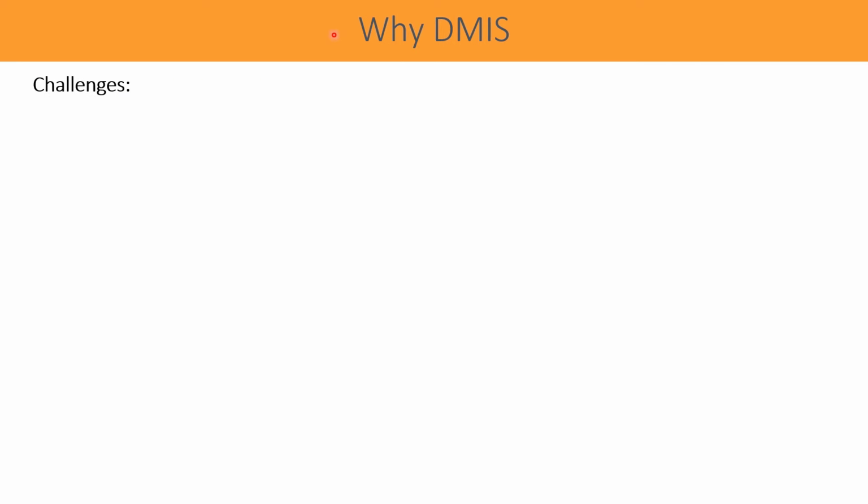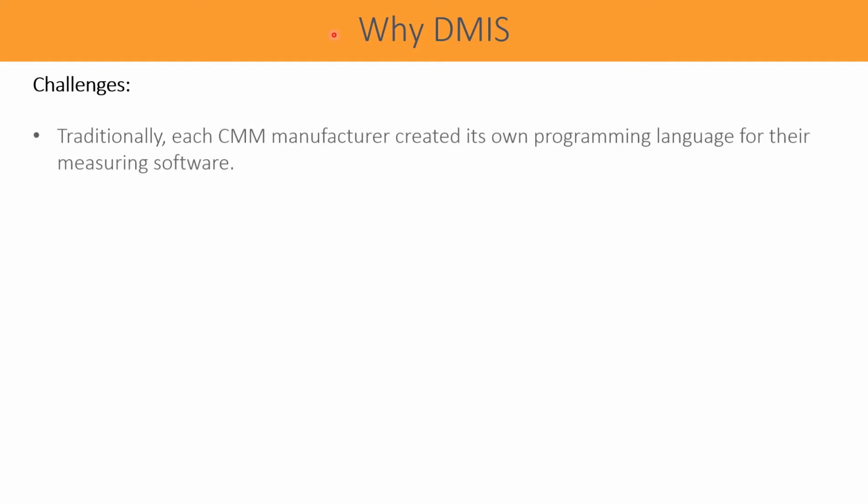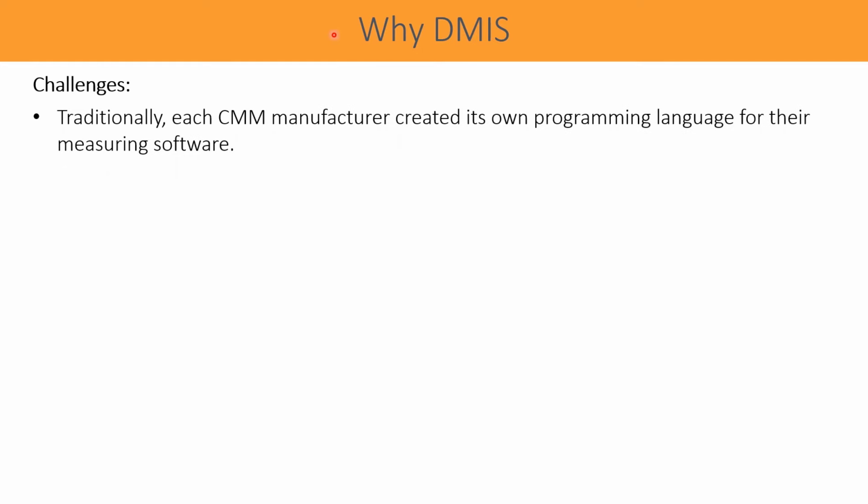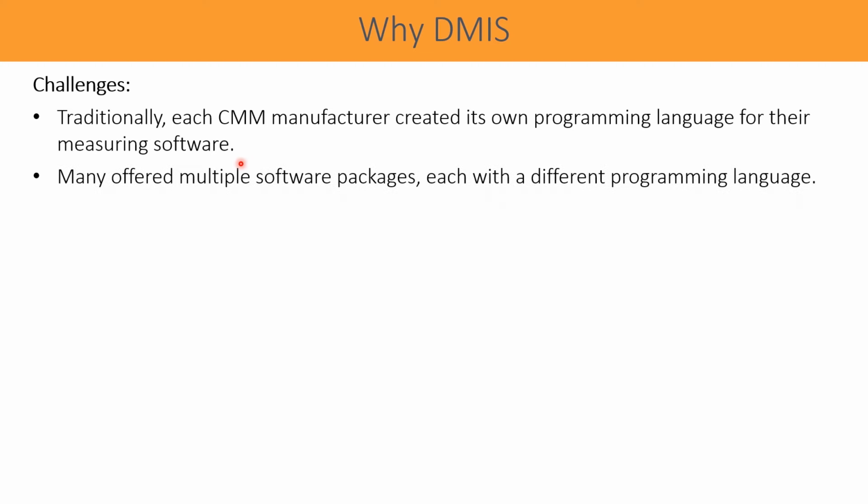What made people develop a DMIS standard? Let us discuss a few practical challenges users and organizations were facing before. Traditionally, each CMM manufacturer created its own programming language for their measuring software. Many even offered multiple software packages, each with a different programming language.